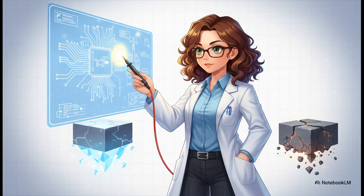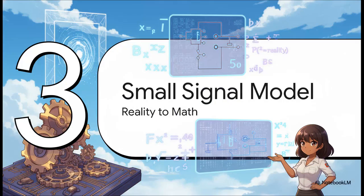If you take one thing away from this, let it be this golden heuristic. Always check your DC Q point first. Seriously, before you ever inject an AC signal into the mix, before you even think about looking at a frequency plot, you have to verify that your DC voltages actually match your blueprint. Because if your foundation is cracked, your amplifier is practically guaranteed to fail. Make sure of that? Great. Let's head into Section 3, the small signal gain model, where we translate reality into math.